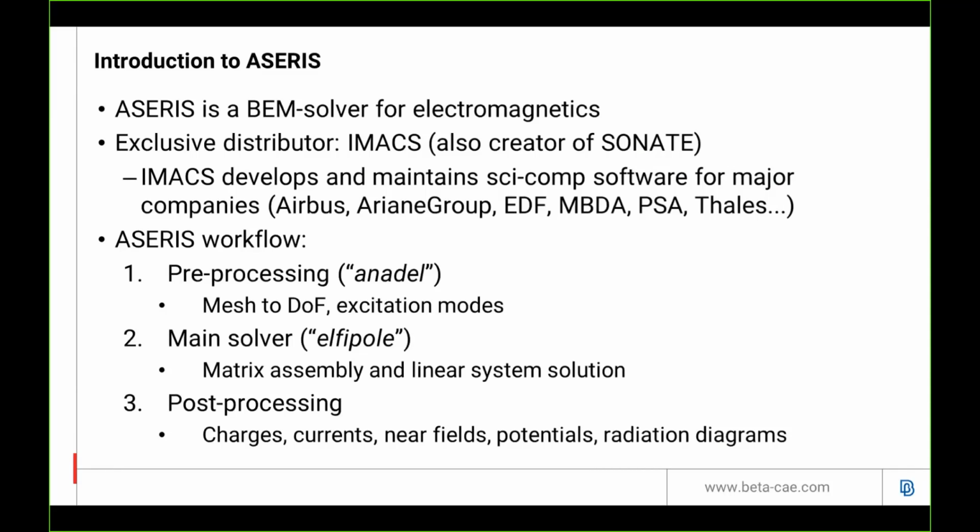The first stage is the pre-processing. So you execute the executable called ANADEL, which converts the mesh to the degrees of freedom that you need for the electromagnetic problem. And it also calculates some other quantities, which I will not go into right now. The main stage is the ELFI-POL solver, which performs the matrix assembly and the solution of the linear system. And finally, you have the post-processing.